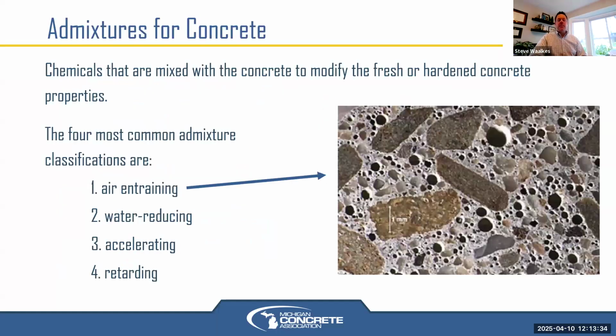So real quickly on chemical admixtures, there's 4 main types. With exterior concrete in freeze-thaw environments, which is pretty much everyone on this call, except maybe in Southern Arizona, you don't generally need air entrainment for freeze thaw. You probably do in the northern and mountainous parts of the state. Same thing with Florida. Southern Florida generally doesn't use it for freeze thaw. They may do it for reduced density reasons, reduced weight in a structure, for example, to reduce that density and reduce the weight on that structure, but occupy the same amount of volume.